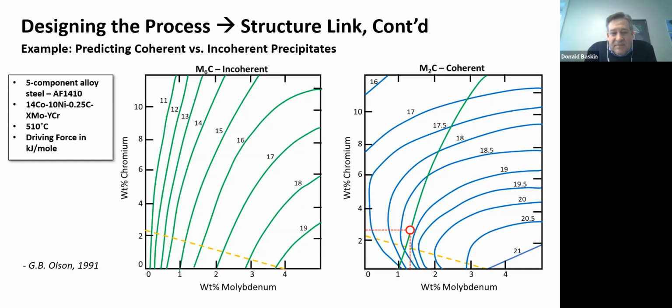The problem is that some of this is evolving with time. I spend hours over the weekends trying to clean this stuff up, and so that's why I haven't given it to her, because I'm still working on it to some extent. You change the thermodynamic data by 1%, and these curves can change. That's right, and that's why you can put a little bit different cobalt in here, for example, and these curves change dramatically. So that's the fun of this. That's the interesting complexity of this, that these different compositions come together to make minute changes, but they get big changes in how the material strengthens or doesn't strengthen.